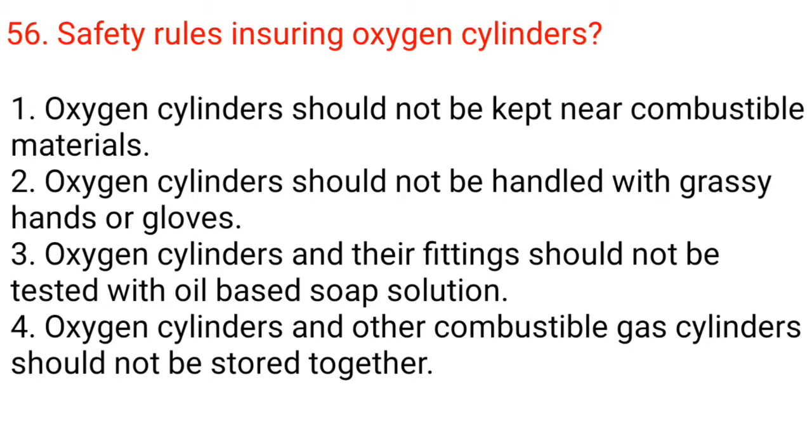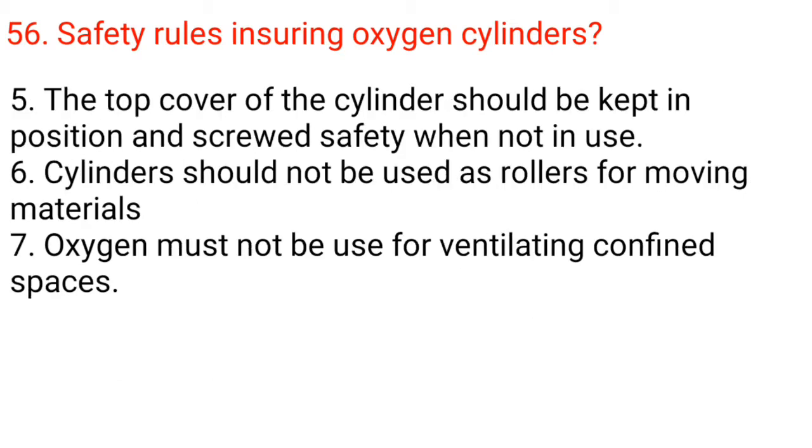Oxygen cylinders and other combustible gas cylinders should not be stored together. 5. The top cover of the cylinder should be kept in position and screwed on safely when not in use. 6. Cylinders should not be used as rollers for moving materials. 7. Oxygen must not be used for ventilating confined spaces.